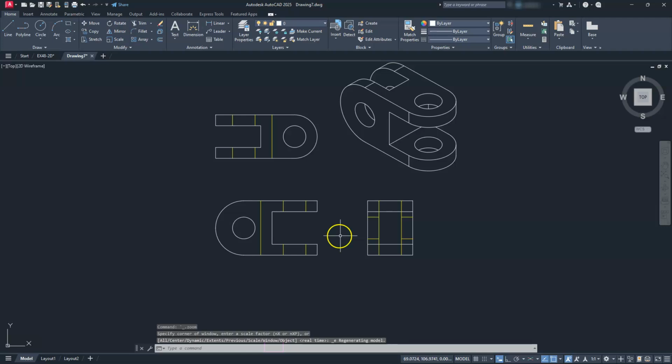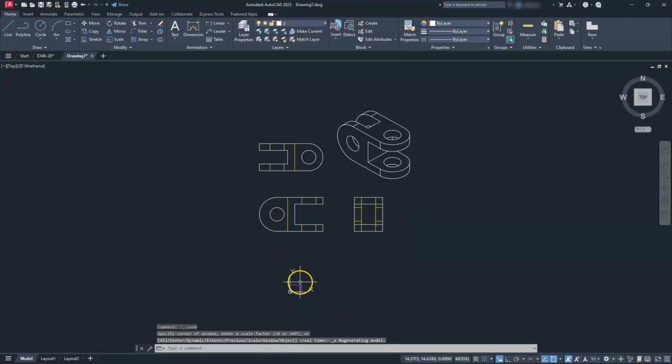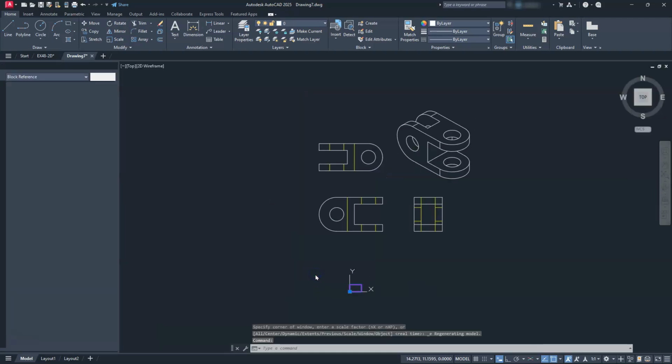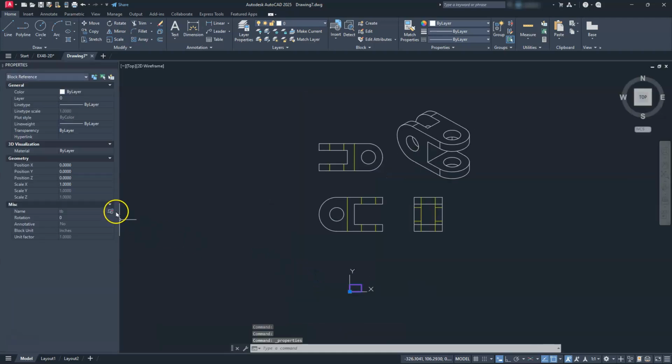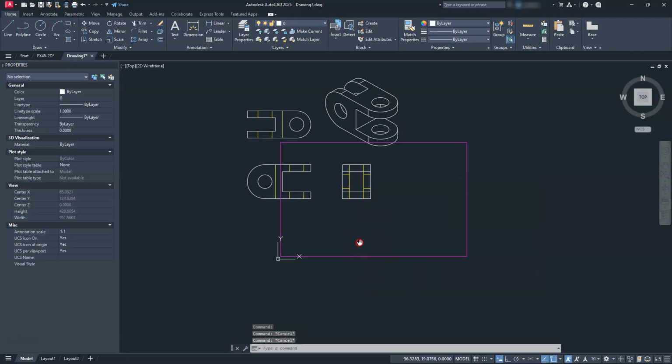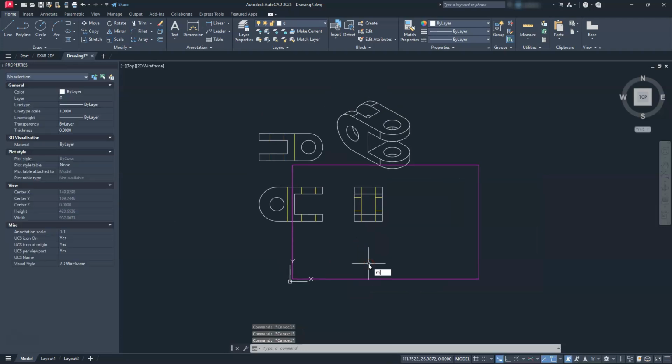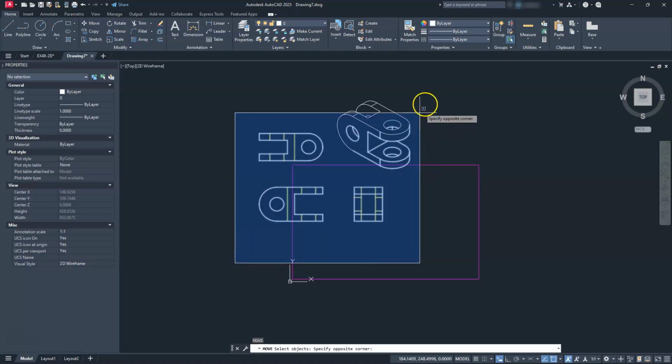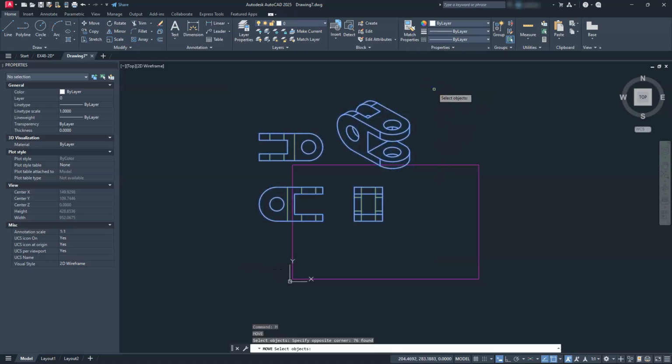And now we get to play around and figure out what the scale factor is, right? So I'm going to select my title block, right click, go to properties. And let's see what 10 looks like, a good gauge. And you can see that 10 is close. I'll next go to 16. And I'm thinking 16 should be the winner. Let's go ahead and move all of this stuff to the inside.